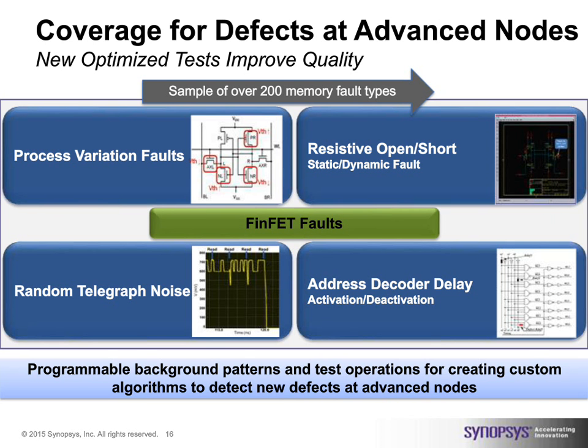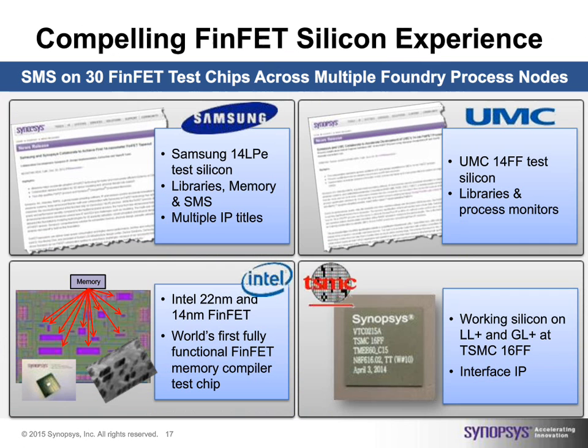While at the Planar technology, we looked at process variation in detail, understanding how it happens in silicon, how it gets manifested, and how we need to detect and fix it. Also, we looked at resistive faults initially, looking at how opens and shorts can be resistive. That is, they are not detected immediately by a single operation, but rather they need multiple operations to be detected. And we moved forward on different blocks of the memory, up to the addressing block, looking at what's in there, which brought us to a set of solutions that can be applied now on FinFET.